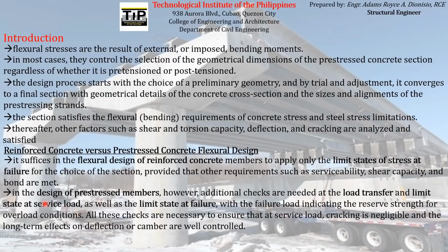That is the main reason why we are conducting pre-stressing on the concrete element, because we want to control the tensile stresses that will be experienced by the element as it supports the intended loads that it is supposed to carry. We know for a fact that those external loads experienced by the concrete element tend to produce what we call tensile stresses on the concrete element, and concrete has a very low strength to resist tensile stresses.